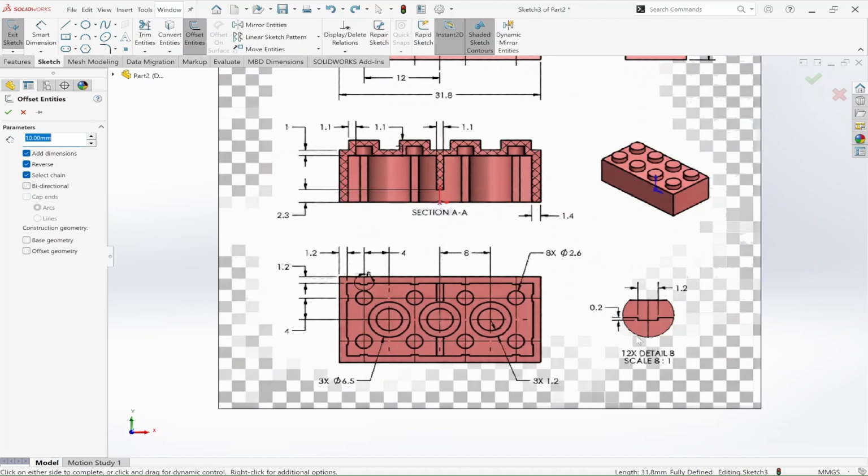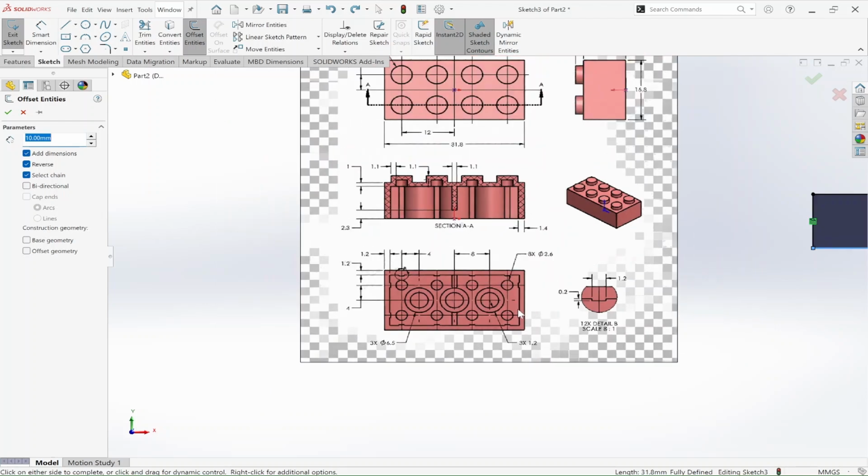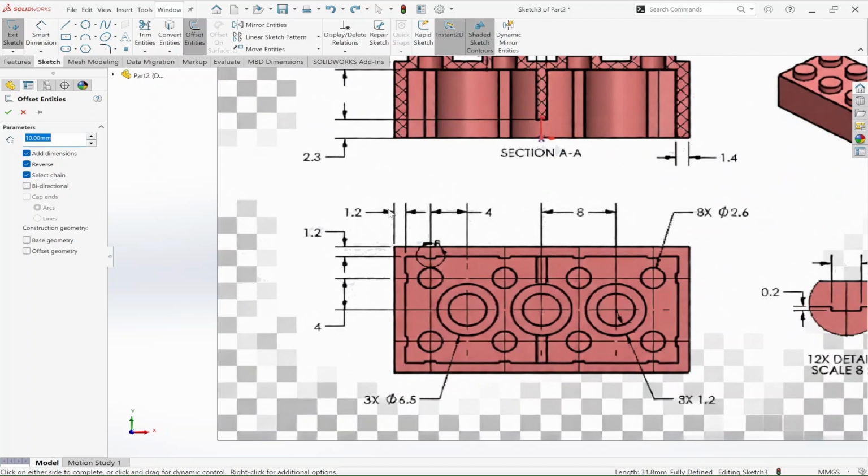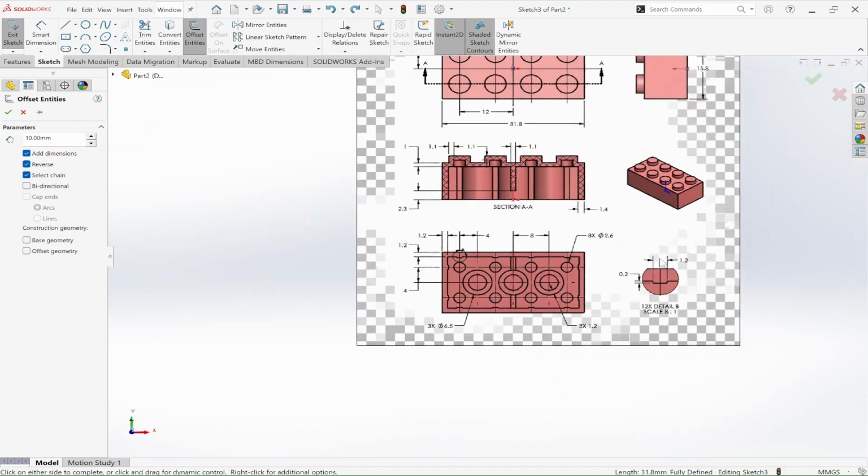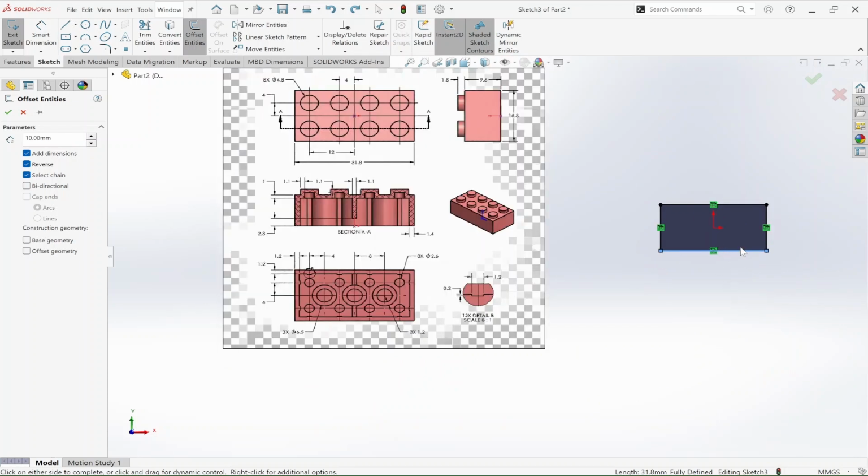But actually it is this cutout height minus 1.4. So the actual thickness is 1.2 mm. I'll show you in the other way also. As you can see, they have mentioned the thickness here, 1.2 mm. So they have excluded the cutout height and only mentioned the thickness of the wall, that is 1.2 mm. So if you want to be a good design engineer, you have to analyze your drawing very sharply, or else you will make this small mistake and your model can go wrong.